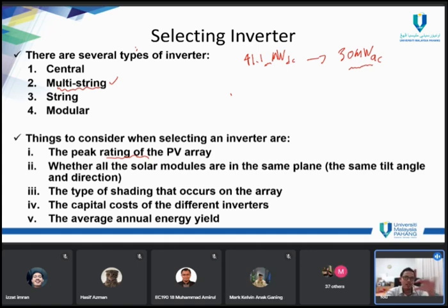Okay, when we're talking about the solar farm 50 megawatt, it refers directly to the AC type, which is the total of power exported to the TNB. It is the rated power that is written in the solar farm in general. In their name, 100 megawatt means 100 megawatt AC. Mostly. But in order to know how many DC, usually you need to refer to the contract. You need to see the contract or any information given by the owner. Then you're going to know what is the exact size of the PV array.